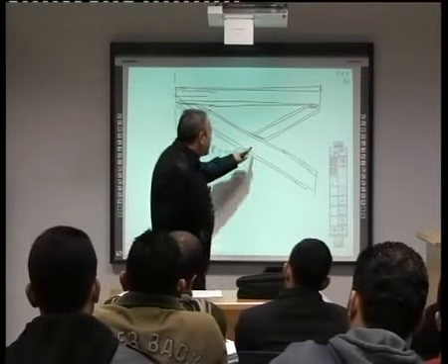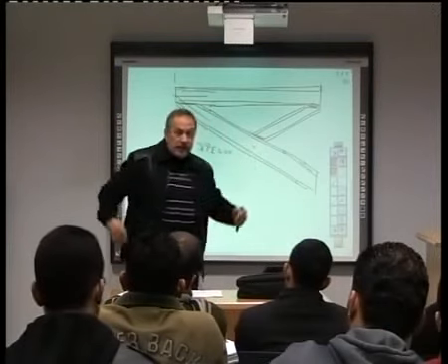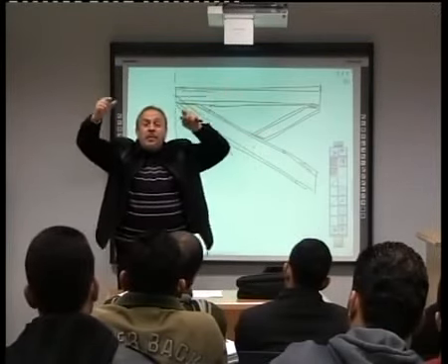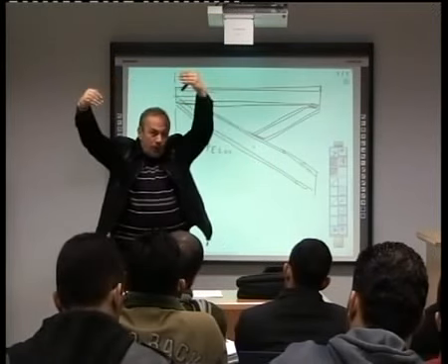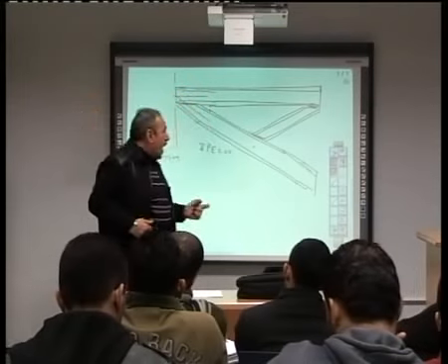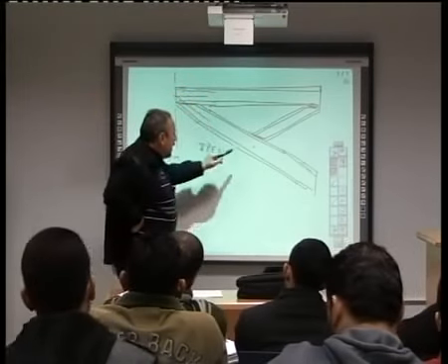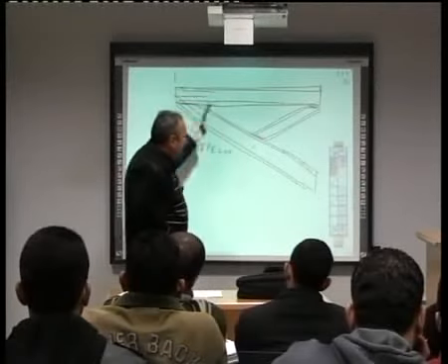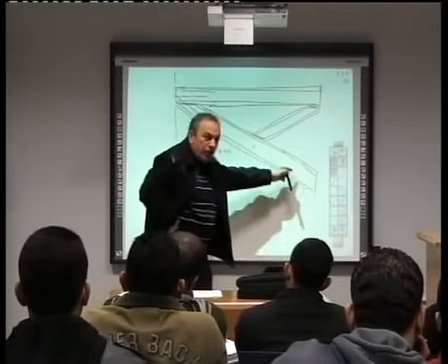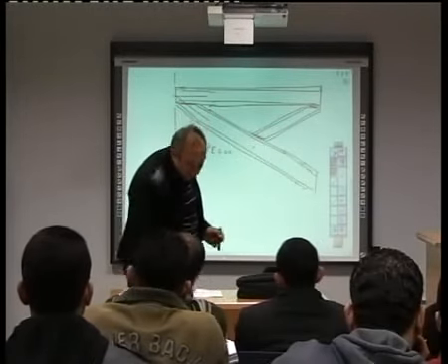Now, what does it mean that I don't have bracing in the middle? This is a 3-hinged arc that cannot be braced in the middle. It's just an arc made to carry the loading. According to SAP, he assumed L to be between this point and this point. This is what SAP assumes. Now, unfortunately, if this member is going to buckle this way, then the whole length will be valid. Let us see what will happen.